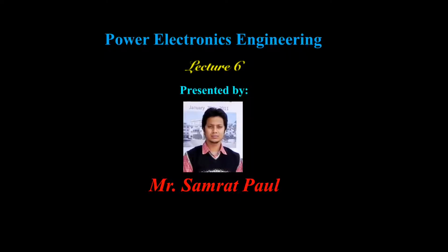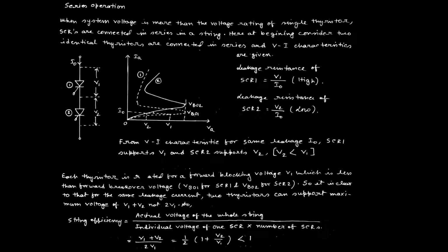That is why for high voltage applications, they should be connected in series, and for high current applications, they should be connected in parallel. So today I am going to discuss the first topic, that is the series operation of SCR. Here we consider two identical SCRs connected in series to demonstrate the series operation.